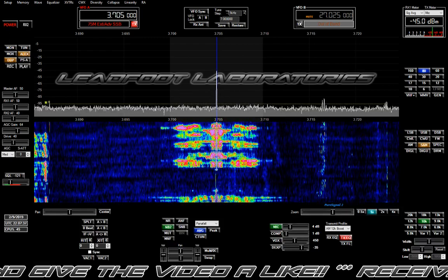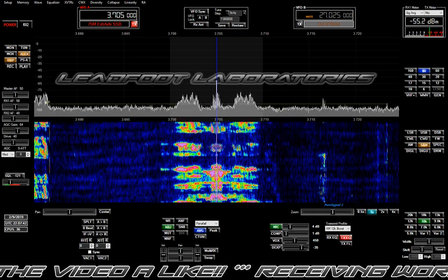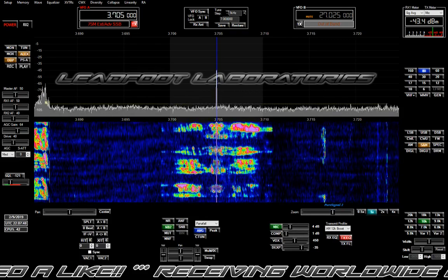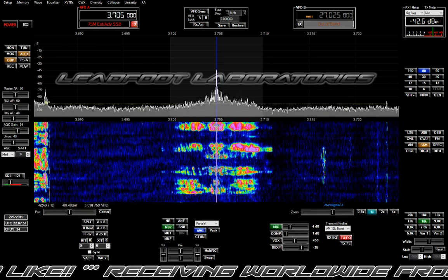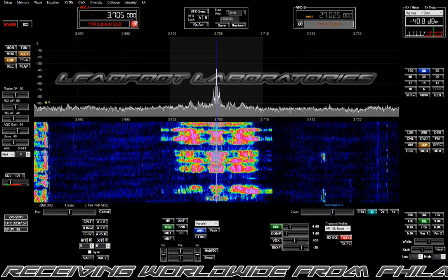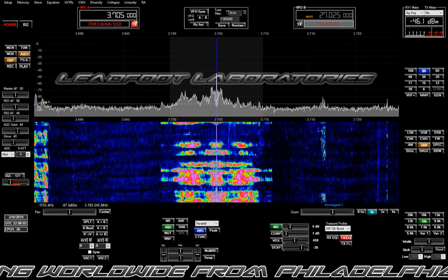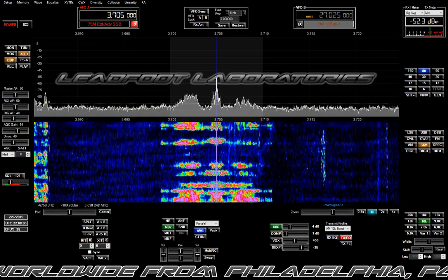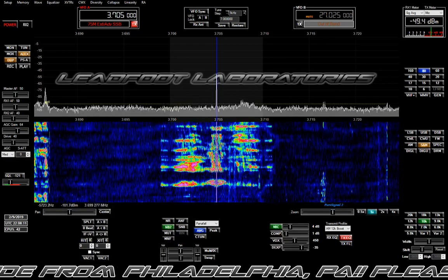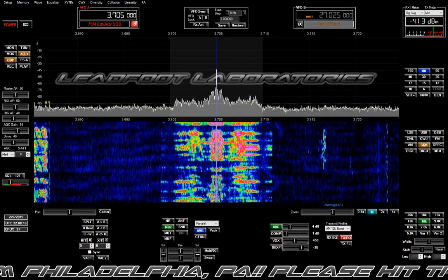Okay, well, what I'm seeing is you have a lot of energy out to about 6K. And after that, it gradually rolls off, maybe about 6 dB less, around 8K. So that's what I'm seeing here. It's a gradual roll. It's not a brick wall like you're seeing with me, pretty much, because this is an SDR and it's got the DSP bandwidth limiting.